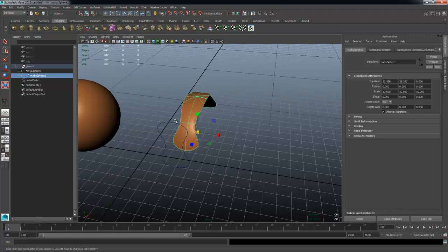The main issue with creating NURBS surfaces is that when we trim them, cut them up, and do whatever we need, we end up with the end result as a NURBS surface, and NURBS surfaces are very difficult to manipulate in the UV space, purely because it doesn't have the customizable UV coordinates to lay it out in a more specific way, in a custom shape, so that we can texture it properly.